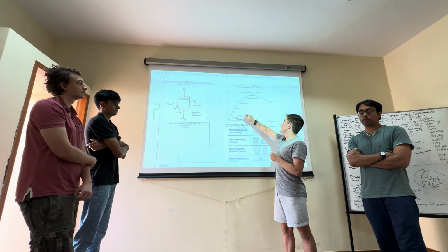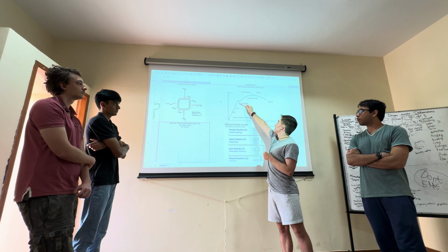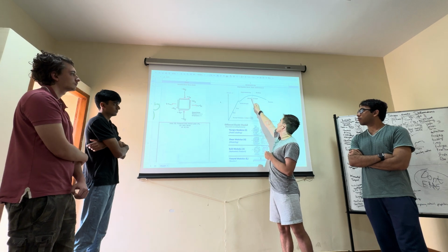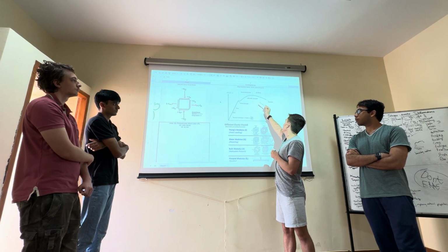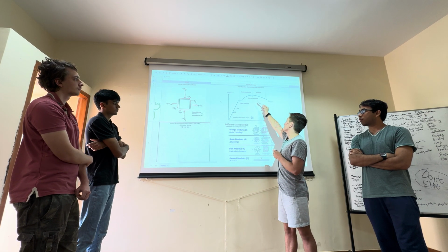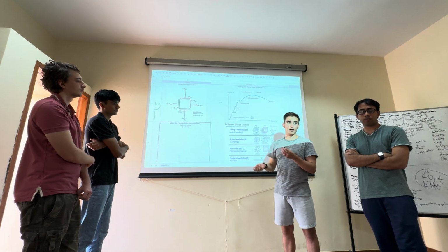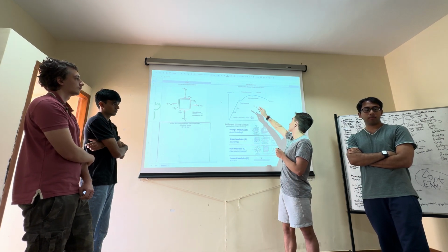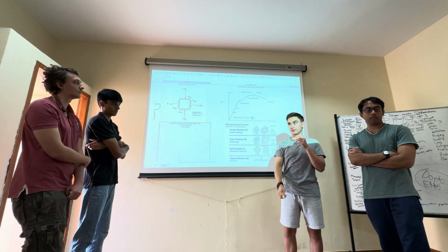After the linear section, you'll have a slight drop before the strain hardening occurs, then the necking occurs, and then eventually the fracture. The ultimate strength is, of course, the highest stress that occurs before the necking, where it drops off and then eventually fractures.